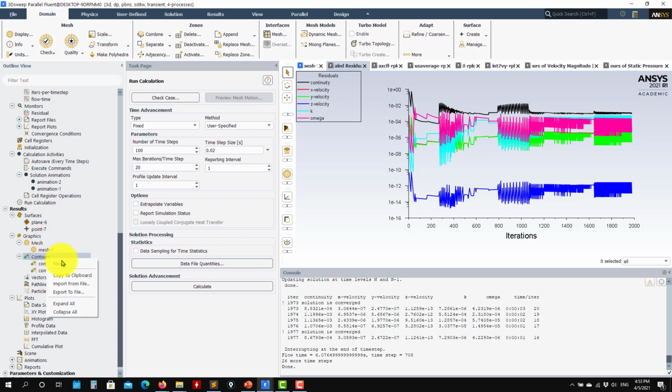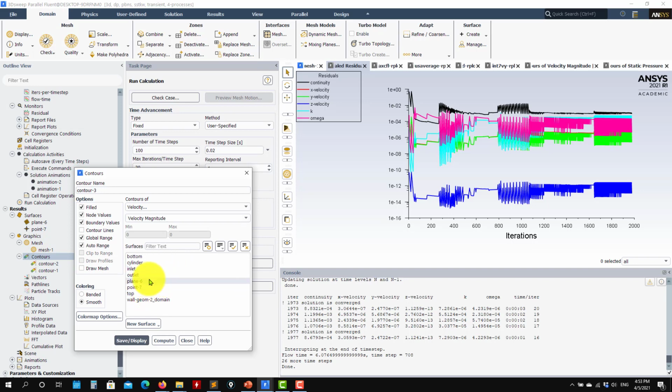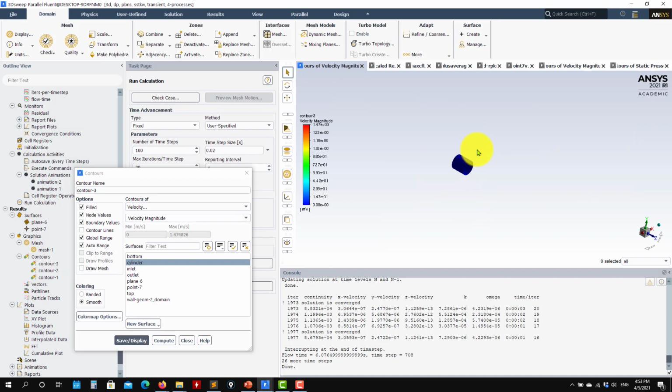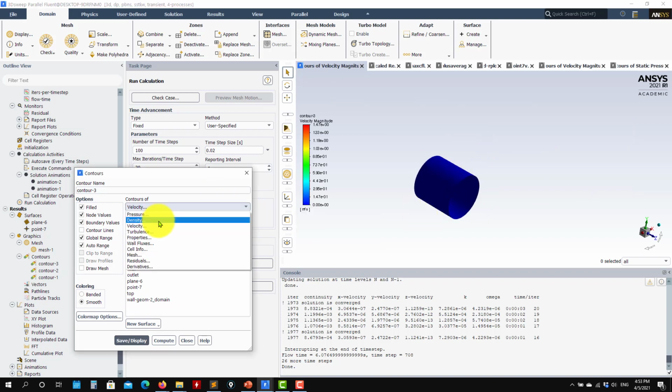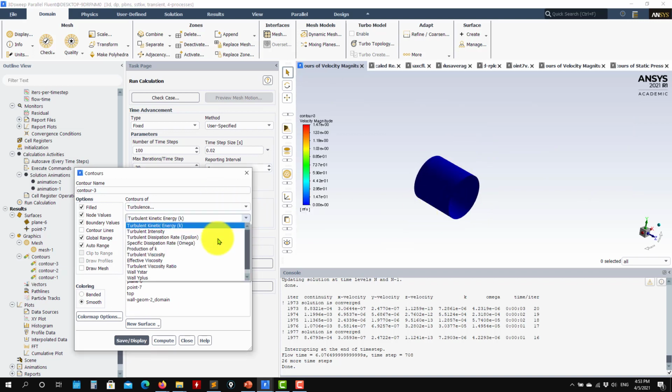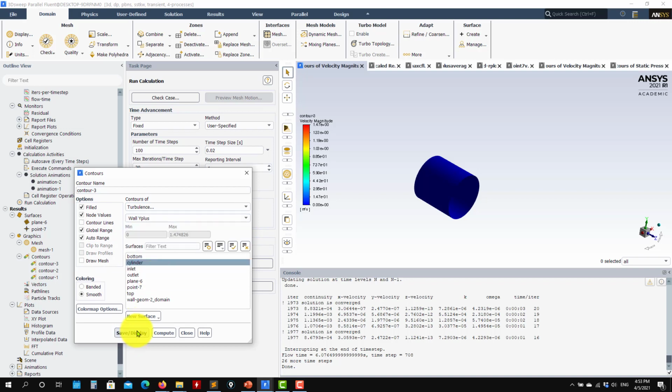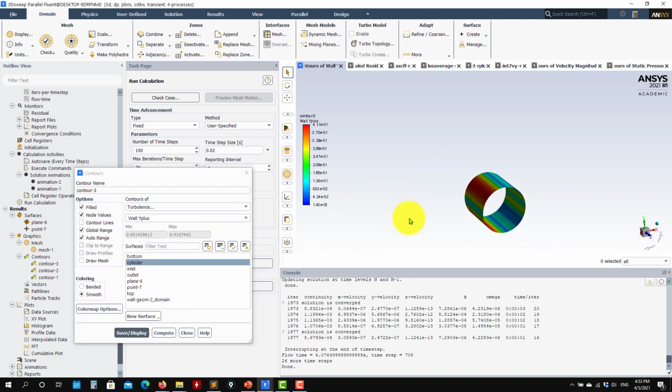So if I go here now, new, and I want to post-process on the cylinder wall, see that now this is a surface, so it's easier to see, for instance, the Y plus value. Remember, previously in that line it's difficult. So see that now you have this one. This is why I prefer to post-process, to run the 2D cases like this, because post-processing is easier. But theoretically your solutions will be the same, okay? Your case setup is exactly the same. I will show you that later.